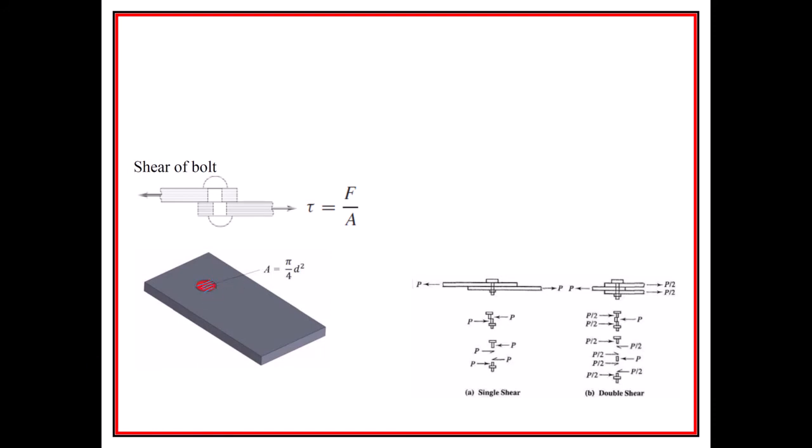And even though, truth be told, that shear wouldn't be evenly distributed across the bolt, this is an approximation or a model, right? It's probably going to be shearing more in the center than over to the side. And if we remember from transverse shear, we did have a distribution. But in direct shear, when these loads get really closer to each other, closer to the supports, we go ahead and make the approximation that it's evenly distributed across the entire face, even though that's not true.